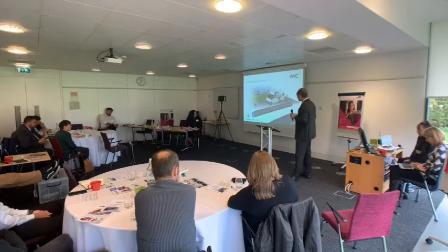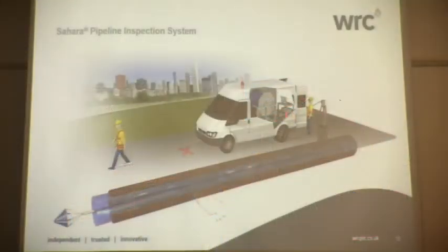We've coupled that with a locating device so that now if you detect the leak with the sensor, the operator at the vehicle is able to stop the cable, position the sensor at the leak, and use the locating device then to pinpoint the sensor, which if it's sitting directly over the leak, they can put a mark on the ground and identify exactly where that leak is. And this is something we've actually been using for over 20 years now, particularly with Thames Water, and I'll come on to some results that we've got from that system shortly.